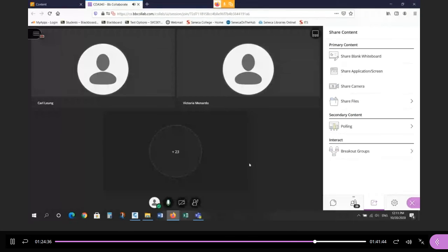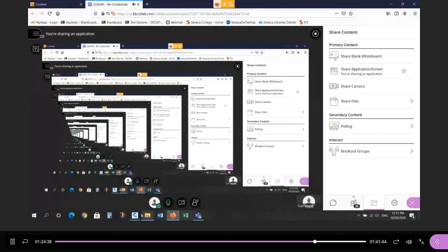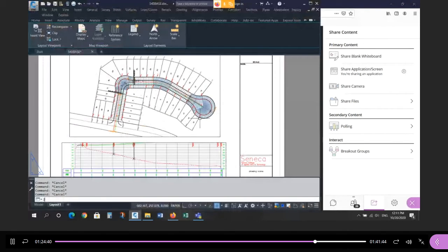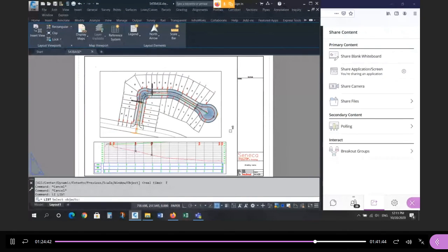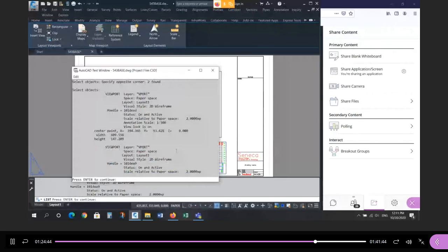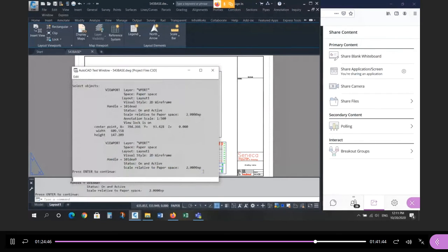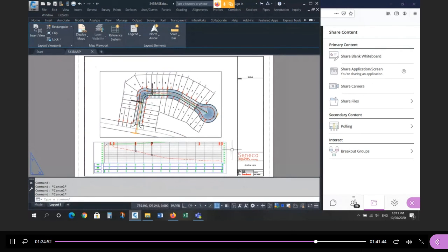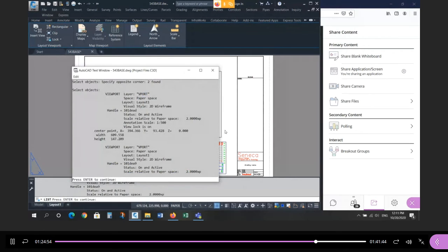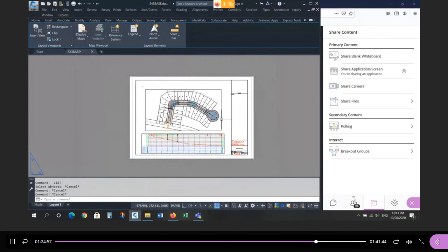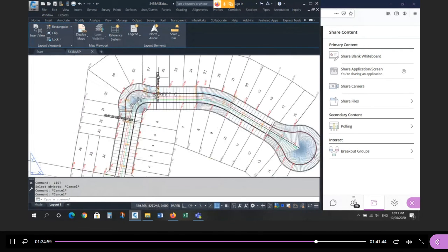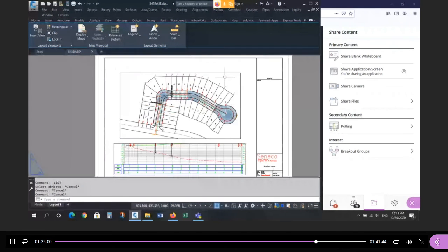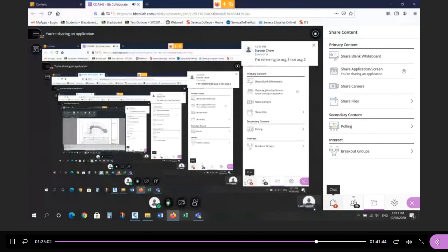So for Paperspace model space setup, this is what I did. So when I open up your drawing, I go to your Paperspace model space, I list both of these frames, and I make sure they say 2xp, which means if I click on one, it's 1 to 500. Okay, 1 to 500. So that's how I know the scale is correct. That's part of the technique. The other thing I look at is, did you rotate this correctly? So when it comes to the rotation,